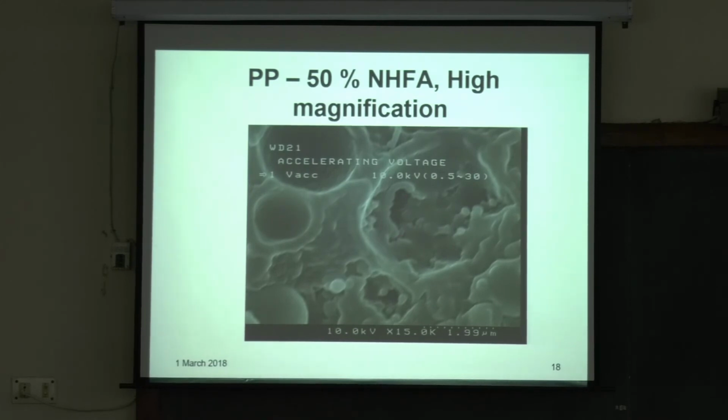So this is some fly ash particle. This has the fracture surface with lots of particles. Although impact energy is often considered to be much less because you don't have any time for deformation, the fly ash particles in this case are taking up that energy through shearing. So if something is coming and hitting the component, it has to hit with much more force to make it crack in a brittle manner at a lower energy.